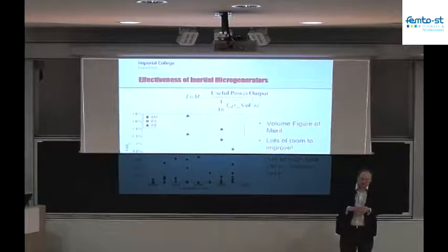So if you've got a device which is this long, you should make the mass this long so that half of the volume is dedicated to the mass and half of it is dedicated to the movement of the mass. This is something that you see quite often that is not implemented correctly for an optimization in terms of the way people build these devices, because people will tend to go for more movement and less mass. But actually you want to be filling half of the total available volume with mass and half of it left for the movement.